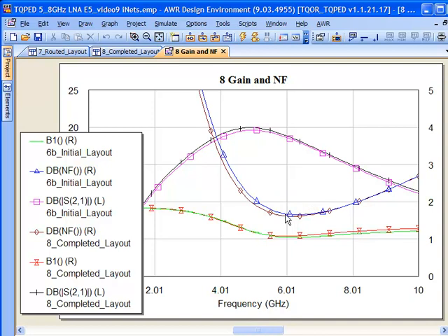So that's our TriQuint LNA MMIC design in a nutshell. We've gone from considering what is noise figure and cascaded noise figure and how we may want to architect our LNA. We've included aspects of a detailed study of the FET and where we should bias it. We've looked at noise circles and stability and maximum gain and minimum noise figure.